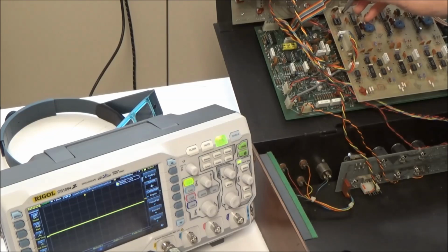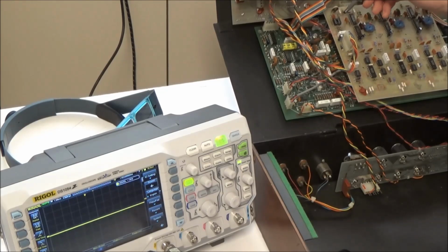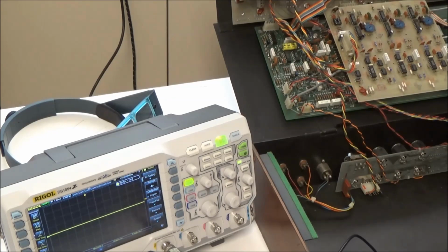But we're now confident that the op amp and the diode won't be affecting what we see on that pin. So that was pin 3, and you can see that there's noise there. There's my signal with the noise. But the noise is there without the op amp, and with the op amp removed, then the diode is out of circuit too. So we're going to have to take a look at what's going on around this area.